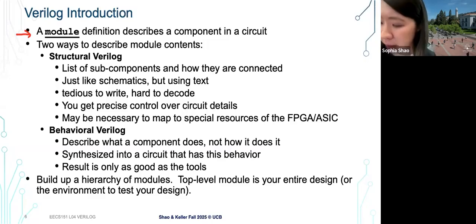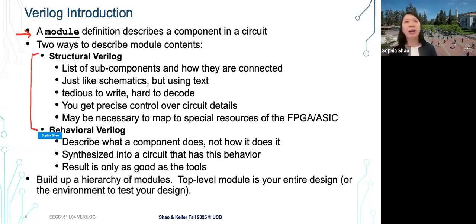In particular, there are two high-level ways to describe your hardware. One is what people call structural Verilog. Those basically literally assemble your circuit using very primitive basic blocks, like AND gates, NOR gates, the very basic logic gate building blocks that we mentioned last week. And then you can use structural Verilog to connect the different components together. We'll see an example later.